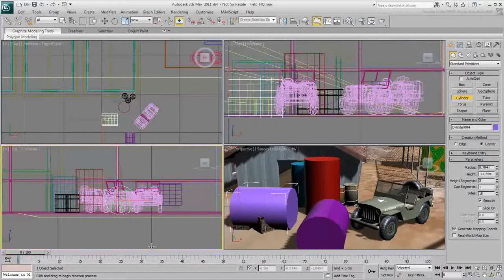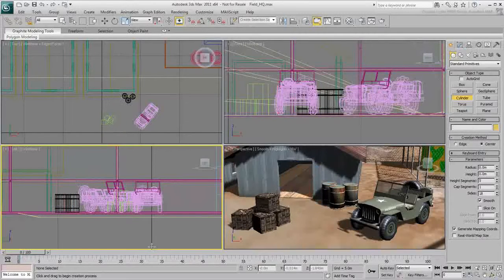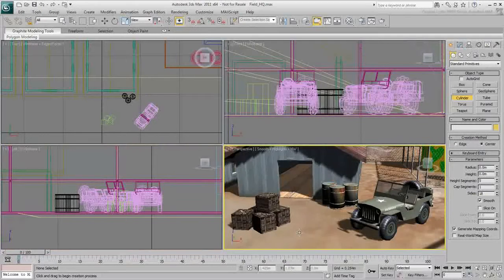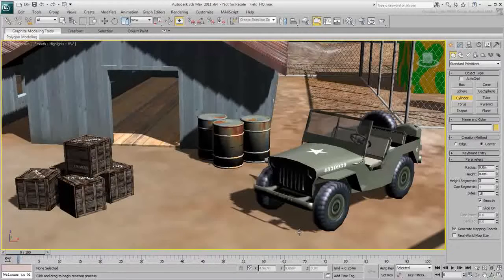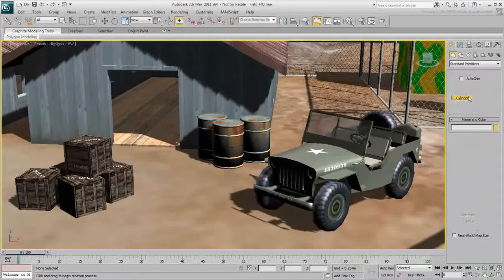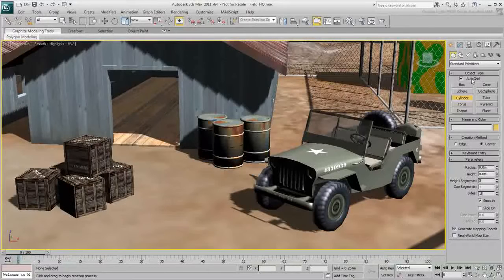You can create more grids apart from the 3 default ones, but it's easier to use a feature called Auto Grid. Let's say you want to build a cylinder, maybe representing a bottle on top of one of those barrels. Activate the type of object you want to create, then enable the Auto Grid option. In the viewport, a tripod appears and updates as you move the cursor across surfaces. This indicates the face orientation of the object, and by creating an object there, that individual face becomes a temporary construction plane for your cylinder. It's good to use Auto Grid on a temporary basis, so make sure to turn it off when you're done with it.